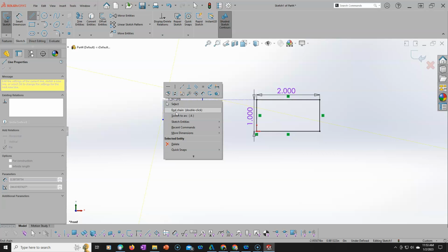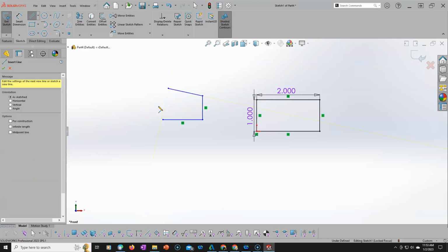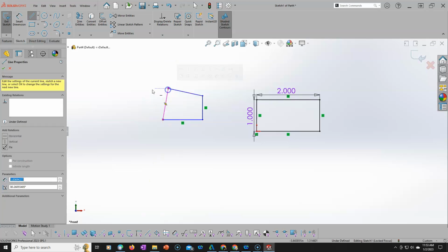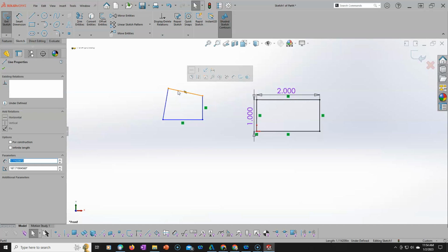I usually end up putting another small tail of a line there, or I can hit the A to switch to an arc. We're not really doing the arcs yet. So let me try the double click. All right, that time it worked, but occasionally I'll get one that is in between. So if I go to connect those, maybe I missed, maybe I decided that I wanted to put something in there. Now I need to apply those relations manually.